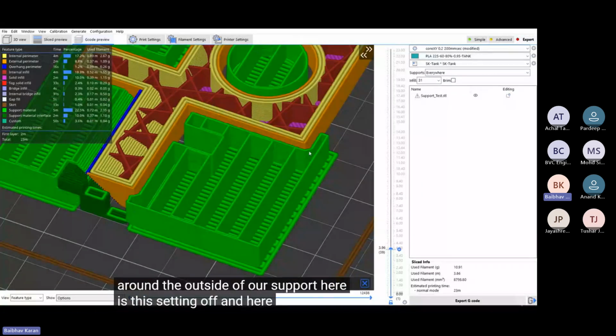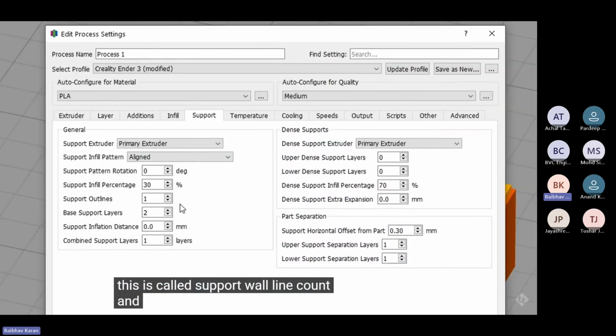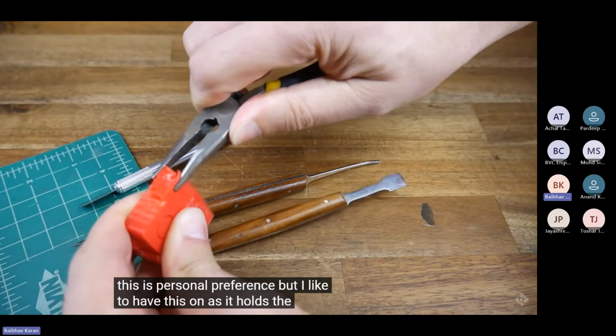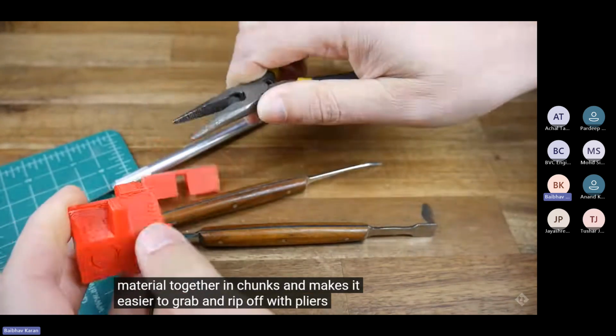Here is this setting off, and here it is on with a continuous exterior wall. In Cura, this is called support wall line count, and in Simplify 3D, support outlines. This is personal preference, but I like to have this on as it holds the support material together in chunks and makes it easier to grab and rip off with pliers.